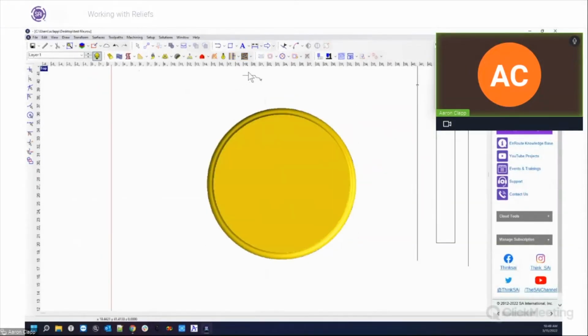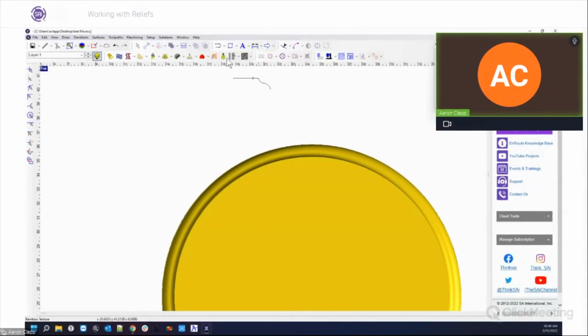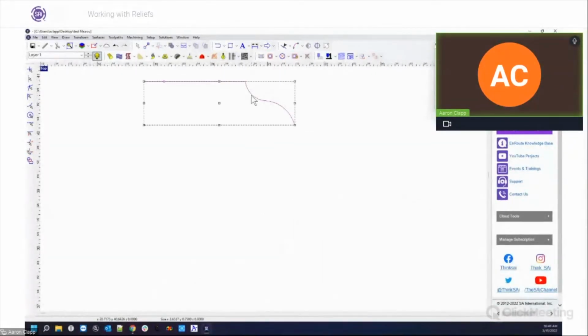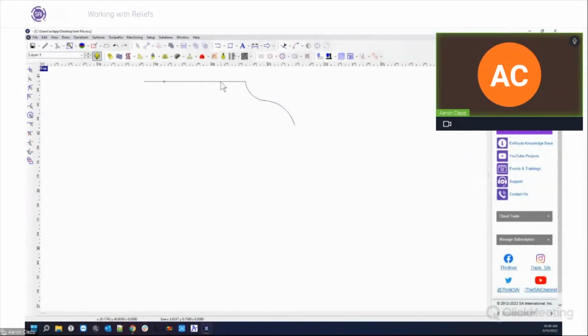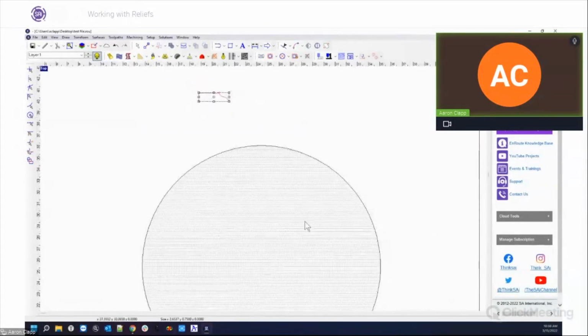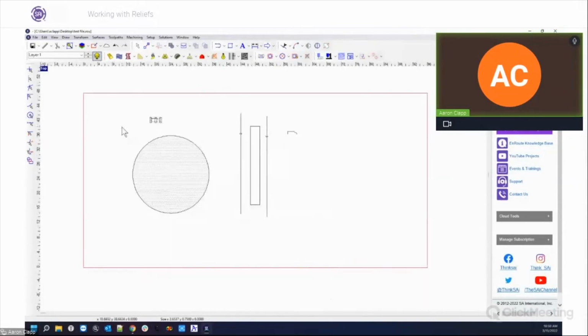And again, you can do whatever you want with this profile. I could come in here and change this however I want. For example, if I right click, edit points, let's see, I could insert a point right here, and then maybe I could grab these lines and make them, I could do all kinds of things. I could specify something specific, or I could be creative and just make something. No matter what I do, this profile will be extracted onto that shape when I run that.